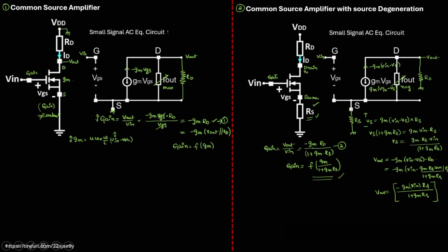So now what we do is, we will be changing the V input over here. So with respect to changes of the V input, let us suppose if you are giving 700 millivolts, the gain might be around 6. If I am keeping 800 millivolts, so input is changed, so that Gm will also change, so the gain will be increased to 7. So as the V input changes, we are expecting that for any value of the input the gain should be constant, but it is not maintained constant. That is a basic problem that we have.